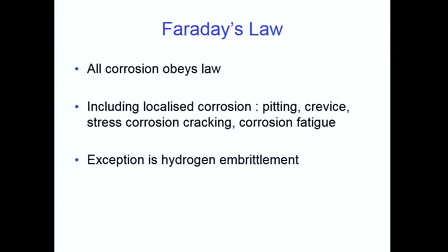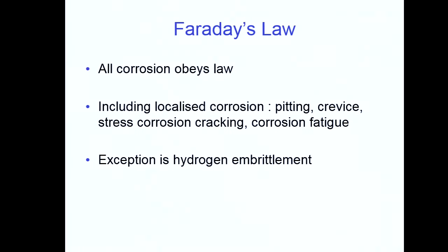So hydrogen embrittlement is not a corrosion process in the same way. Yes, you get cracks in the material. Yes, they will cause failure of the component, but they're not controlled by the current flow in the process.